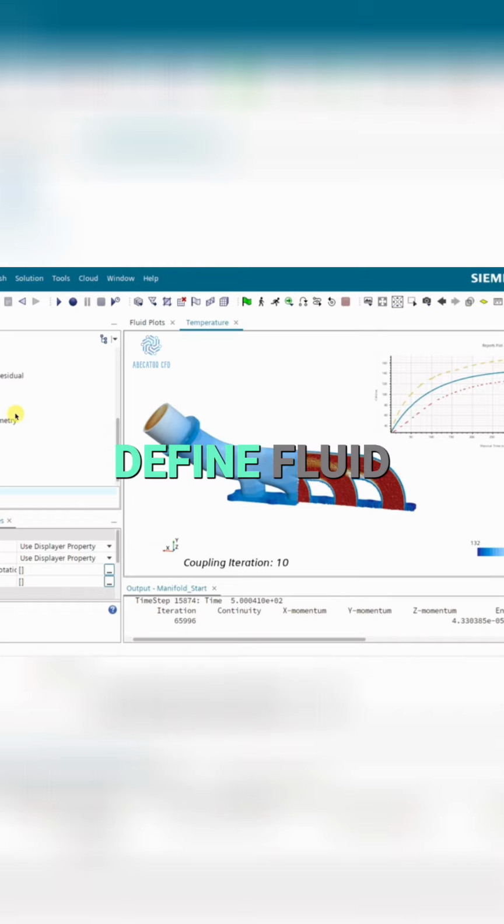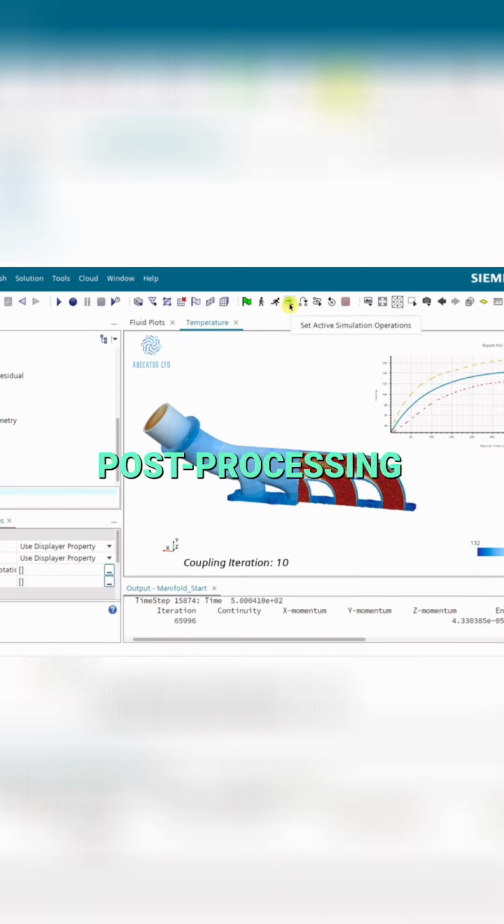We saw how to define fluid-solid regions and how to solve them together. We learned how to set up an interface between fluid and solid so that information is exchanged correctly. We talked about conformal meshing and how to get matching meshes across regions. We went through some useful tips, like how to turn plots into annotations, and how to add those annotations into a scene so your post-processing is clearer and more professional.